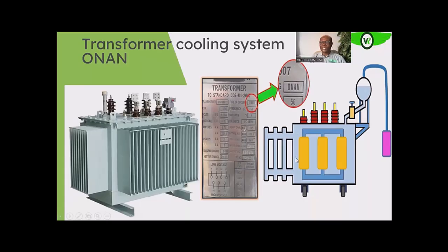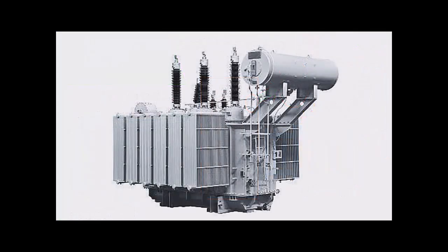The oil that is in the tank covers the transformer winding and the core. So as heat is generated, the oil molecule conducts that heat away from the winding. And naturally, by convection, it will move away from the source of the heat, after conducting heat. The molecule will gain enough kinetic energy to move away. So cooler oil will come, so the hotter oil will move up, and then the cooler oil will drop down. And then as it's moving away, it moves into the radiator fins, okay? And then in the radiator fins and on any part of the transformer too, it gives off that heat to the body of the transformer. And then the air around the transformer removes that heat from around the fins or around the body of the transformer.